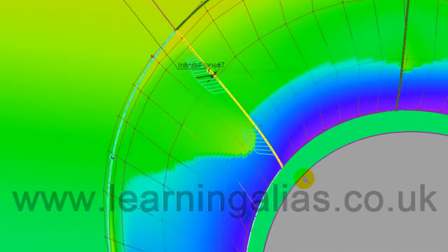I'll tell you the hotkeys as I go if I remember. NUV and sensitivity of 999. Hit spacebar or enter. You can see we've got two combs here. Now what that normally means is that one curvature of CV is too high and one is too low, so we're going to find out what's going on here.